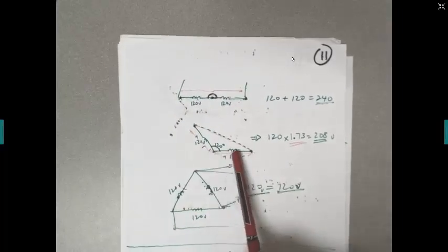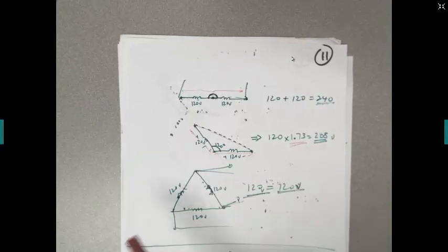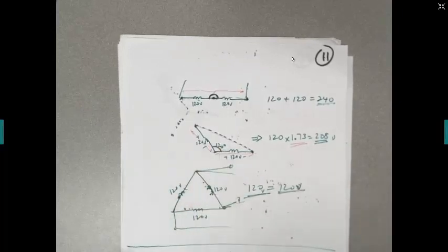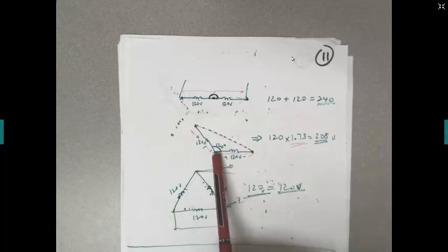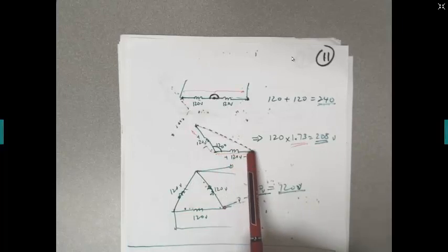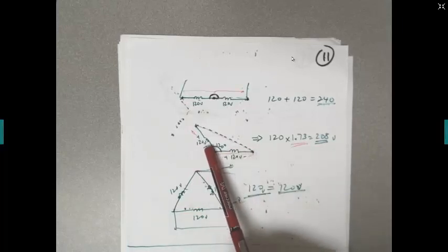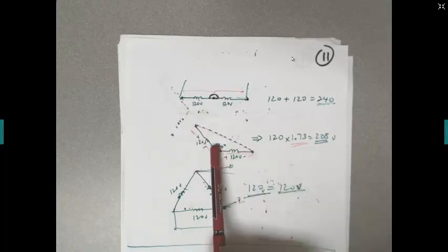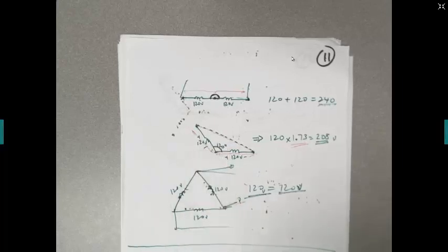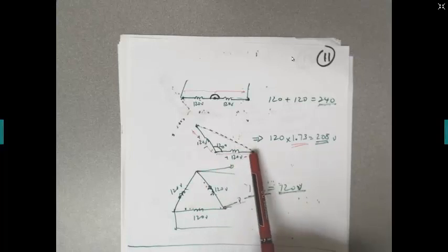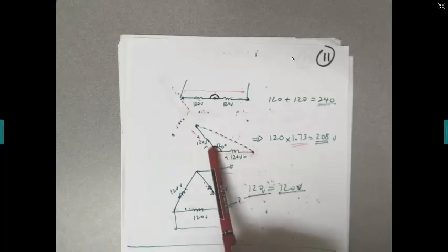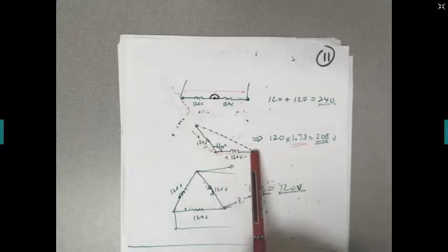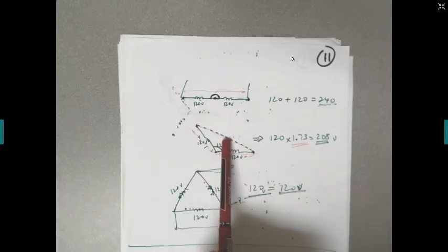When you have two lines like this with a phase angle of 120 degrees, if you look at them as vectors, this vector goes in this direction right here, and this other vector goes in this direction right here with an angle of 120 degrees between them. So when you add this vector plus this vector, you're not going to take this one plus that one. Instead, you take the two ends and measure this distance right here.